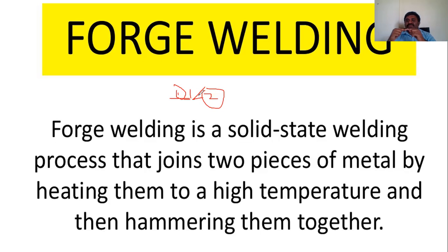We have to consider which way the welding is going to be done here. If a hollow cylinder is there, it may be cylindrical or it may be a tap or whatever it may be, so we have to be careful. Before we go, scale, okay. Before welding that one, we have to remove that scale. And the formation of new scale should be avoided.